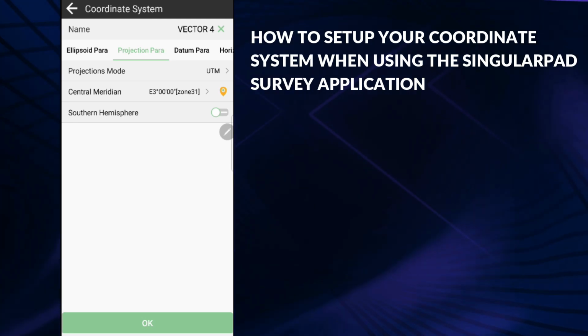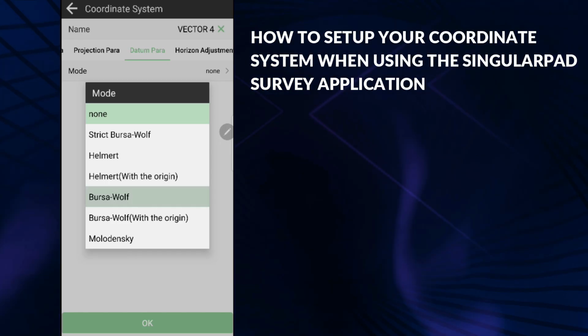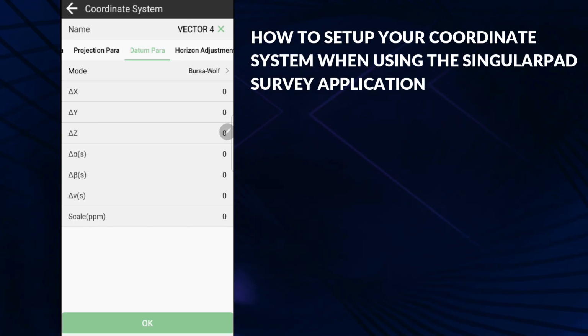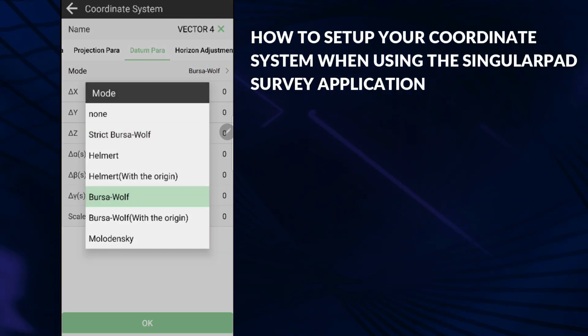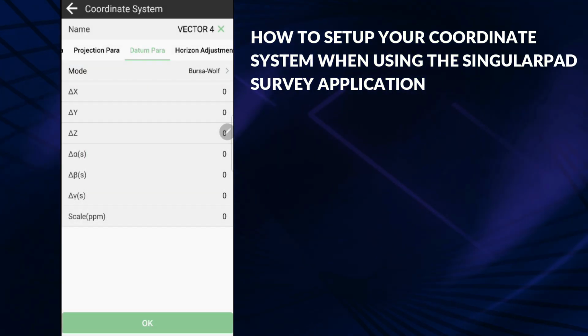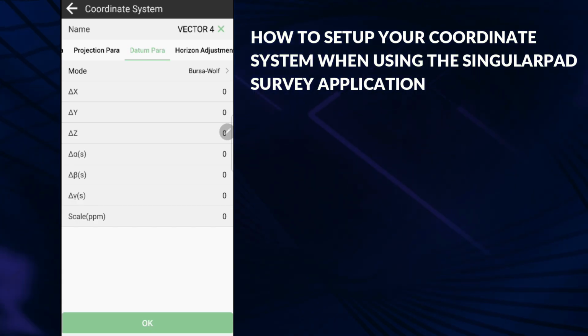And you go to the next page, which is datum parameters. Here you enter your coordinate parameters. So we are going to use a Bursa-Wolf. On Bursa-Wolf, if you are using a 3 parameter coordinate system, you enter just 3, which is the change in northing, the change in easting and the change in height. But if the coordinate system has 7 parameters, you enter all 7 of them. So I'm going to do that quickly.